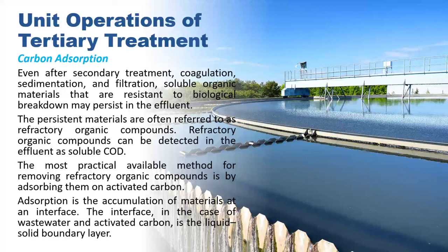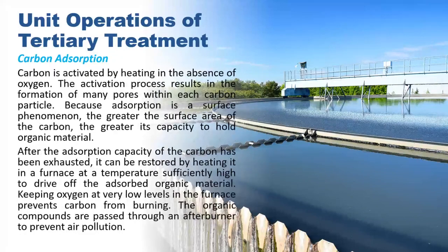Adsorption is the accumulation of materials at an interface. The interface in the case of wastewater and activated carbon is the liquid-solid boundary layer. Carbon is activated by heating in the absence of oxygen. The activation process results in the formation of many pores within each carbon particle. Because adsorption is a surface phenomenon, the greater the surface area of the carbon, the greater its capacity to hold